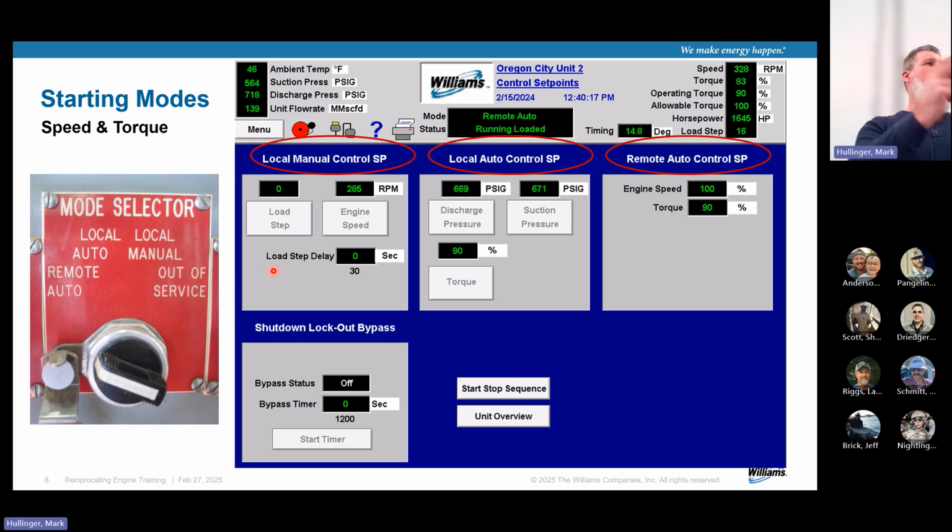They will add or take away the torque on the compressor based on what it's asking for. One of the reasons people like reciprocating compressors is they're flexible in their volume, and you can ask a little bit more or a little bit less, and you're not hurting the driver so much. Turbines, do they act that way?